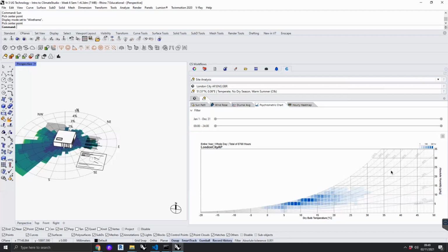So if you want to use evaporative cooling in your hot and dry climate, it's going to work incredibly well. It's going to take all the energy with it as the moisture evaporates. Your only problem is where are you going to get the moisture from?